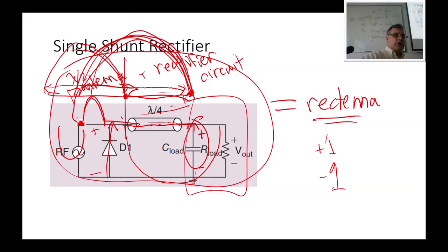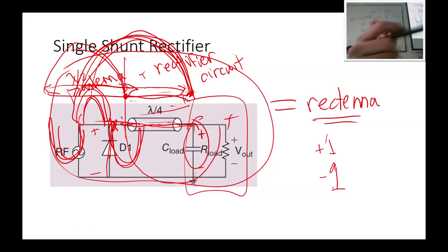This reflection over here converts this pulse into a backwards pulse, a negative pulse, which then turns the diode on and puts more charge over here. In fact, there's a doubling effect because this gets to the end just as the next negative swing is hitting this diode. The two superimpose and you get a doubling effect.